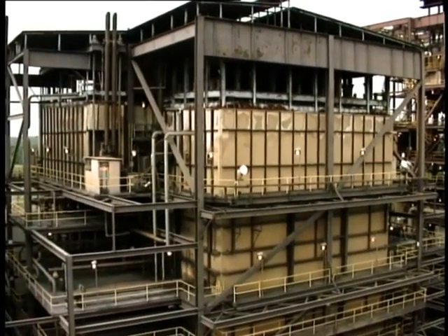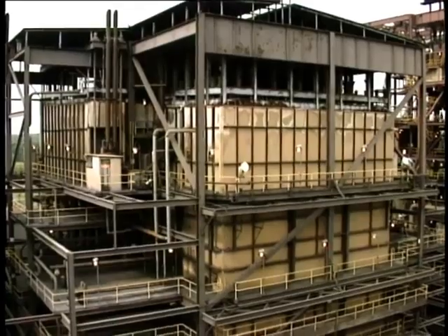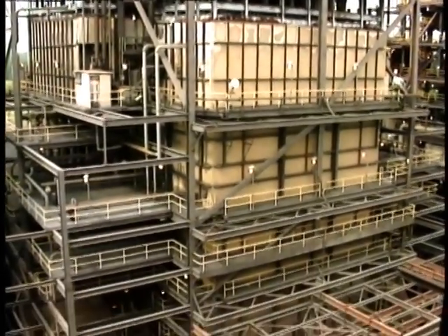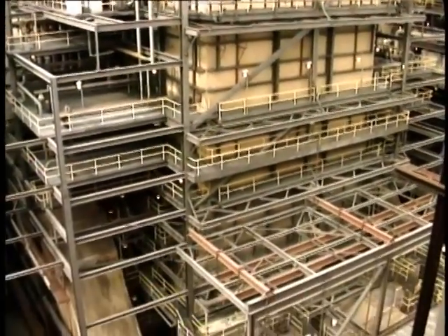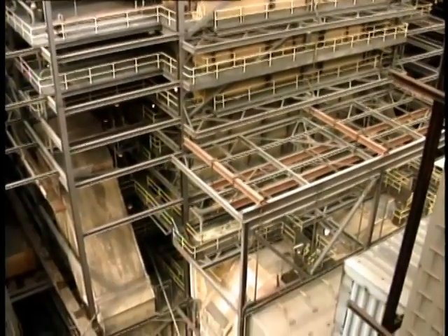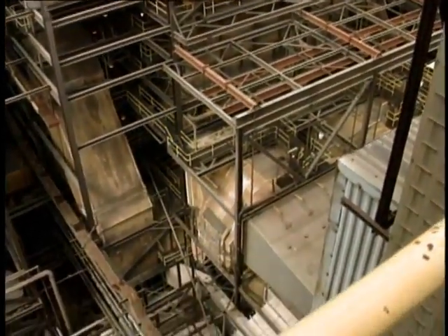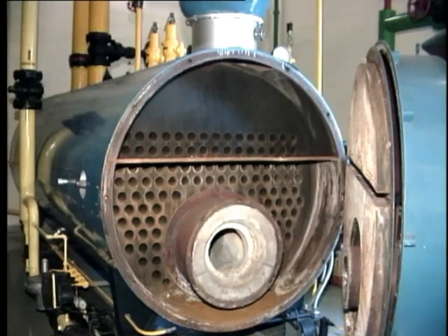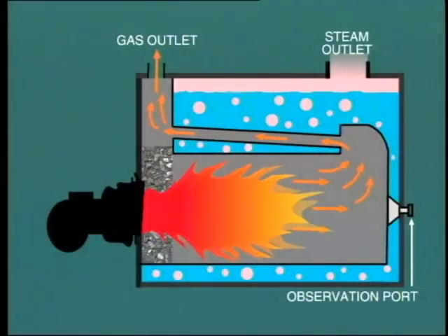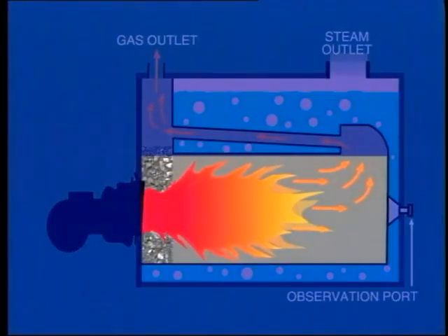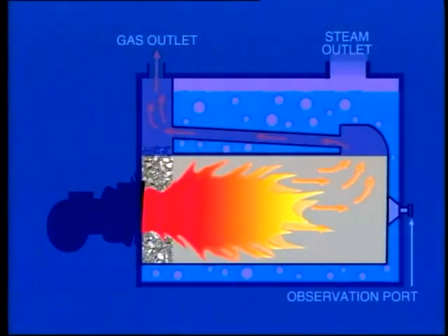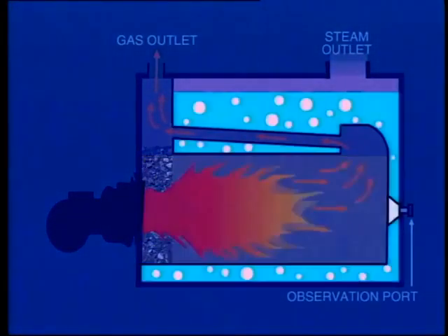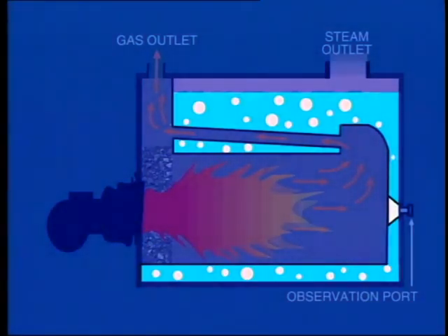Of course, a modern steam generator is vastly more sophisticated and complicated than our diagram, as we shall see. But we are often reminded of these basic requirements when studying boiler construction. One boiler type which is not so different from our hypothetical boiler is the fire tube type. In this arrangement, the vessel is really a cylindrical shell with a large fire tube running down the middle. Water fills the space between the fire tube and the outer shell to a high level.